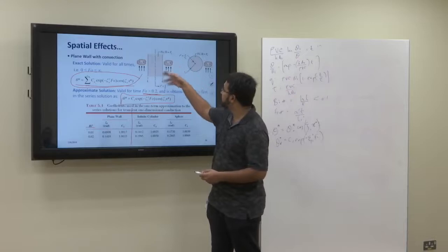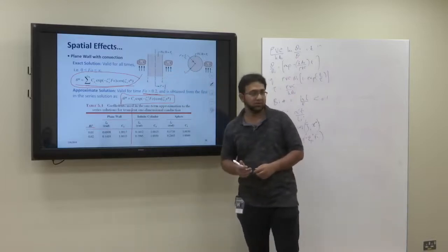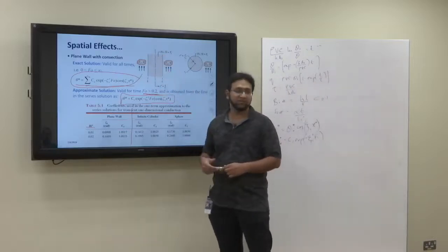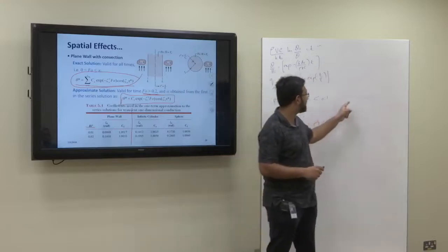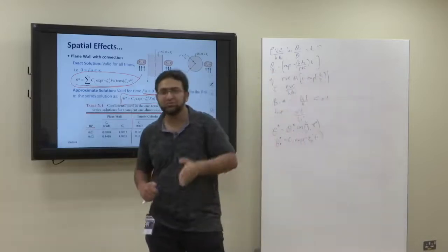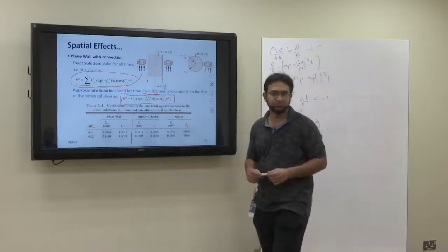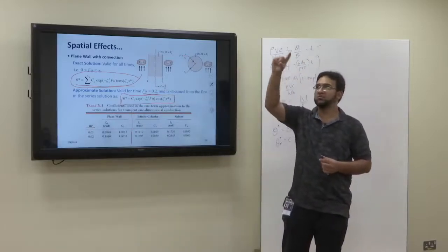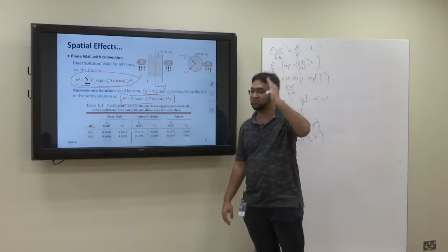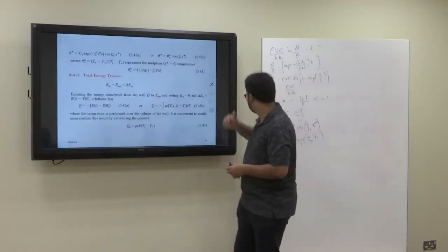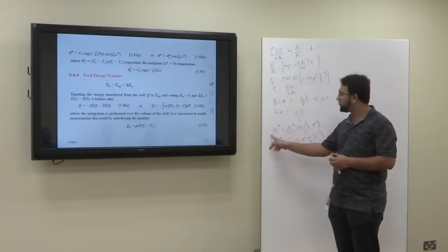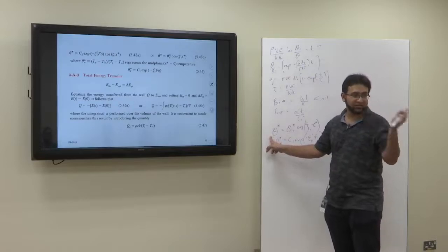Now you need to understand what this theta naught means. It means the temperature of the adiabatic surface. The adiabatic surface is normally the surface where you have the highest temperature. That is the point where the temperature gradient becomes 0, but the temperature is the maximum, where the curve, after becoming maximum, starts decreasing. So theta naught star is like finding the maximum temperature. Based upon the maximum temperature, you find the actual temperature at any point other than the adiabatic surface.